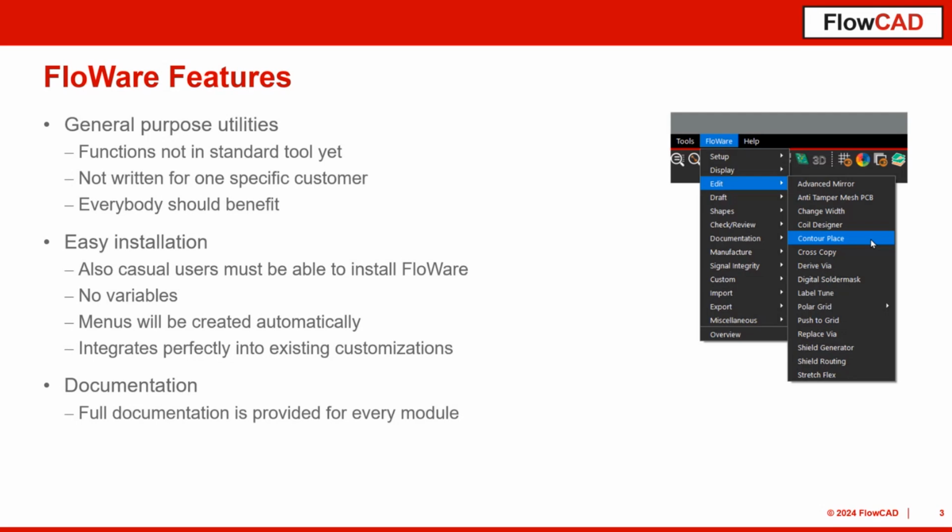But Cadence is a huge EDA company, we all know that, and development resources may be limited. That's why we try to provide a solution to the customer rather than saying, okay, we have communicated this to Cadence and now we wait until this gets implemented. Fortunately, for PCB Editor, Allegro, Cadence provides an automation layer which is called Skill, which allows us to do any kind of automation, right?